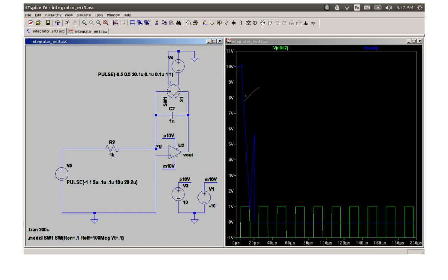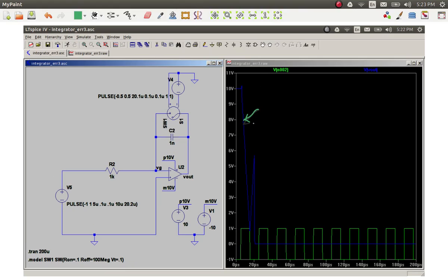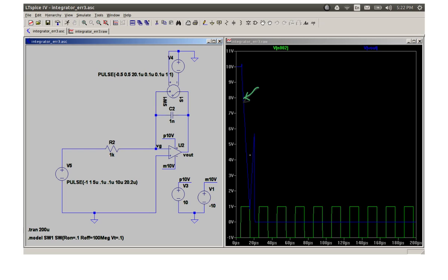This part actually does look like it's a part of a triangular waveform, and in fact it looks like it reaches its bottom point. The voltage is turned negative here, which means since it's an inverting amplifier, this is an inverting integrator. The current gets pumped in when this is positive, which means this voltage is more positive than this voltage. So the voltage is negative, so that's what is happening here. As long as my input was positive, it was +1, yeah.